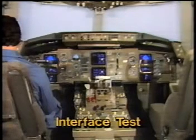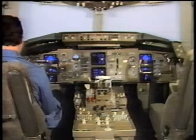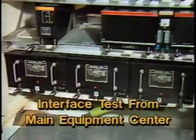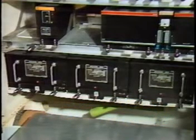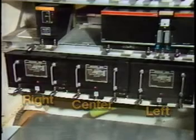An on-ground interface test of the Inertial Reference System can be initiated from the Main Equipment Center or flight deck area. To perform the interface test from the Main Equipment Center, press the test switch on the IRU's front panel. IRS self-tests cannot be initiated in flight. We'll use the left IRU to demonstrate the interface test from the Main Equipment Center.